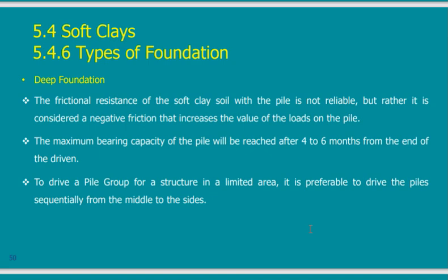So this is what we have to discuss. Frictional resistance of the soft clay with the pile is not reliable, but rather it is considered a negative friction that increases the value of the load on the pile.